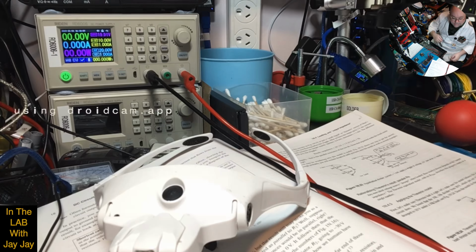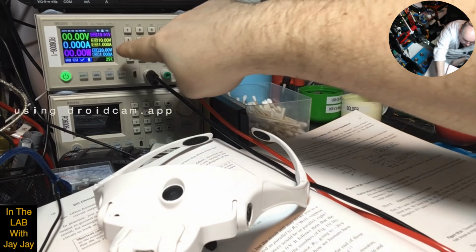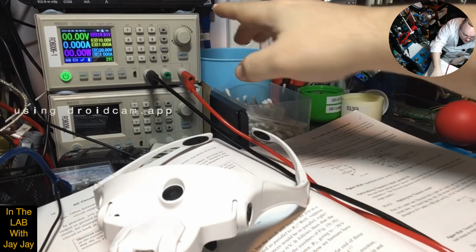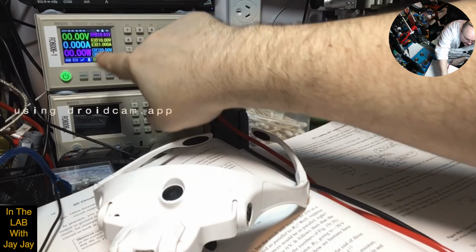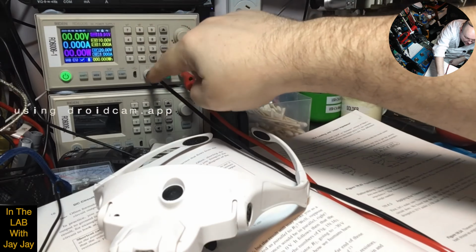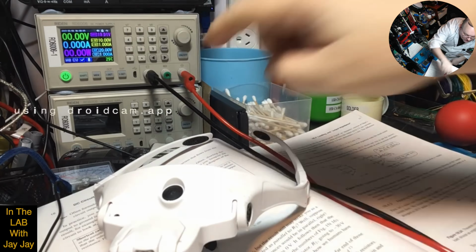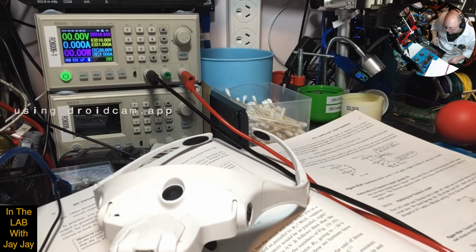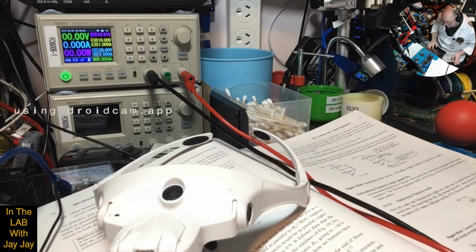All right, so here's the power supply. We've got it set at 10 volts. There's not really much else to show you. It's constant voltage, so the current settings don't matter. The over voltage is not likely to be a problem, but we've got it set at 20 volts and 1 amp. If it goes over that, it'll shut down. So, sorry, back over